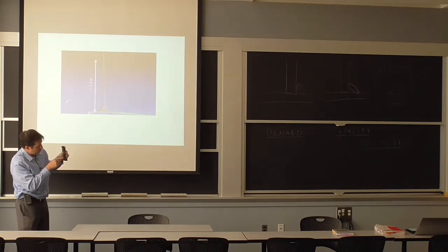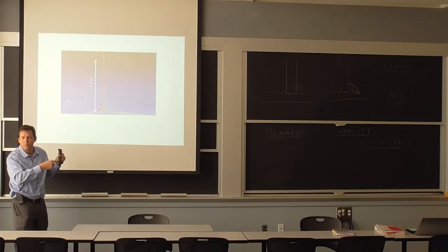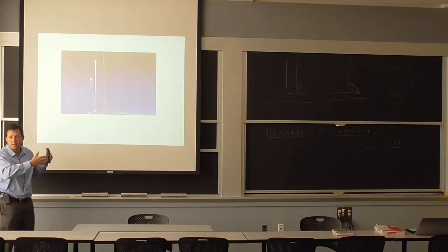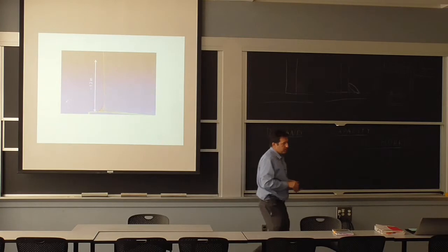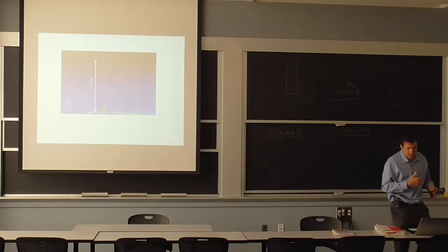So if you're able to move that edge a little bit ahead, there's not a whole lot of stress risers because there are not that many stresses here. So it matters more to position the front leading edge correctly than the radius of it. You want it to be outside the main load path. And that was essentially confirmed from the analysis.